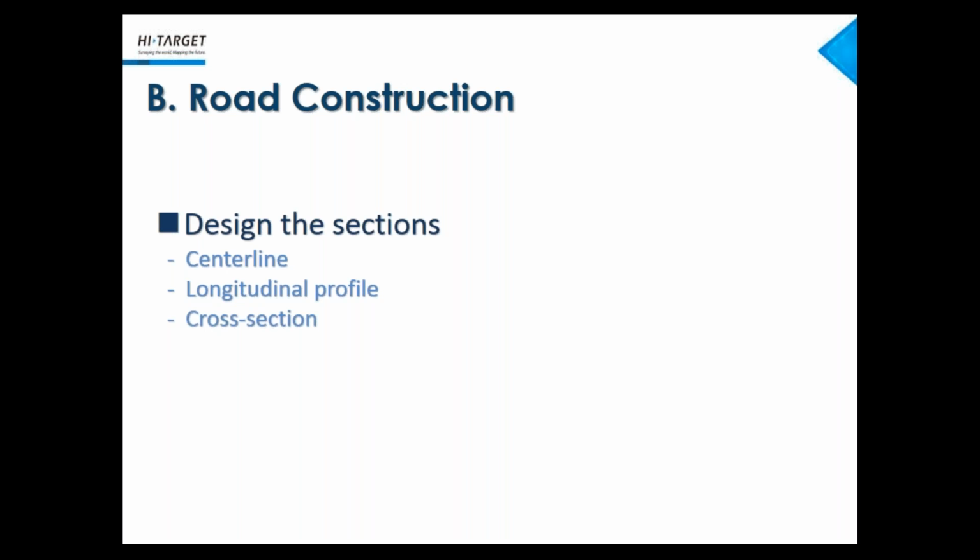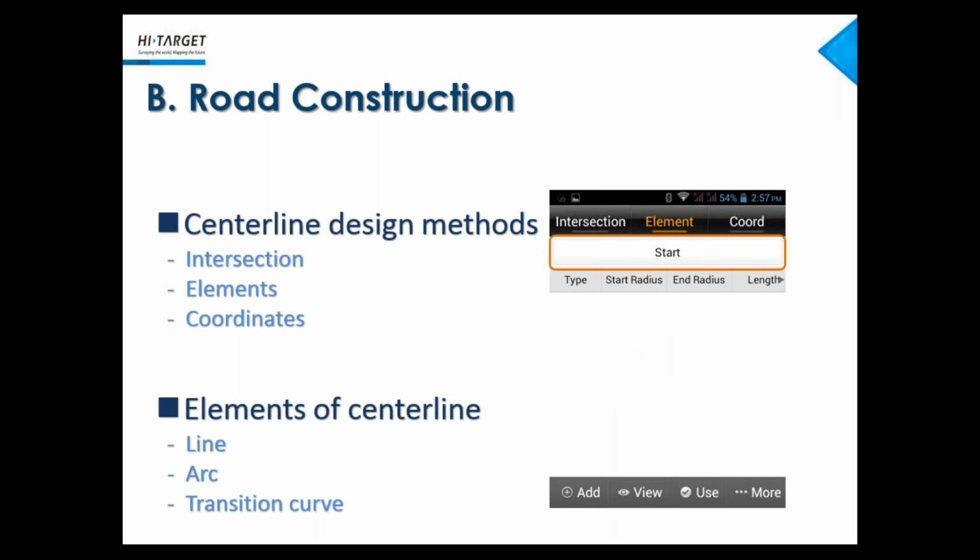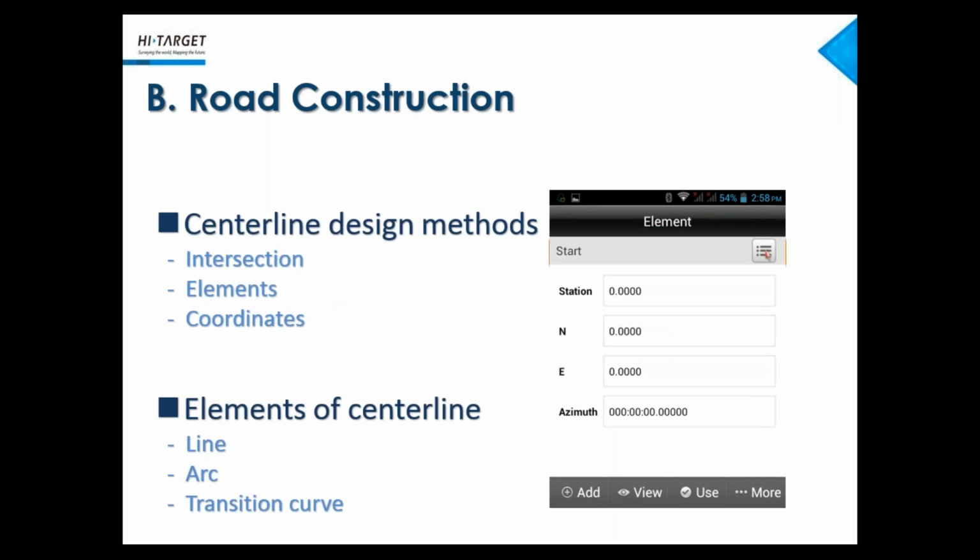That means you will collect the points where we are going to make the road, to collect the current cross section. How does it look like? And then the app will compare it with the files in the app, coming from the profile and the cross section. So it will give you the results, how much you need to cut and how much you need to fill. And also, like what I mentioned, there are two methods here: one is for the average, the second is for the pyramid.